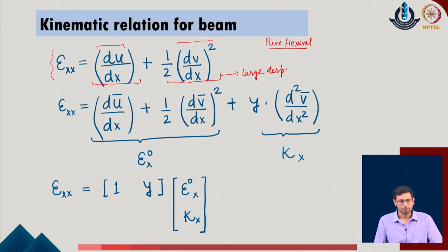Then we considered the expansion of the displacement field with respect to the u parameter, which, if you recall from the last discussion, we defined as u bar, which is the pure extension, minus y times theta for the given problem, and of course this is also in the member coordinates.